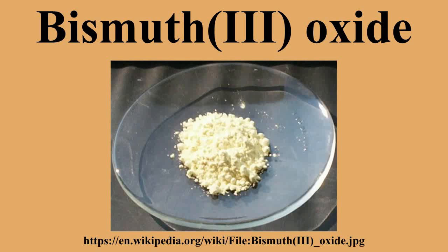The behavior of bismuth trioxide on cooling from the delta phase is more complex, with the possible formation of 2 intermediate metastable phases: the tetragonal beta phase and the body-centered cubic gamma phase. The gamma phase can exist at room temperature with very slow cooling rates, but alpha-bismuth trioxide always forms on cooling the beta phase.